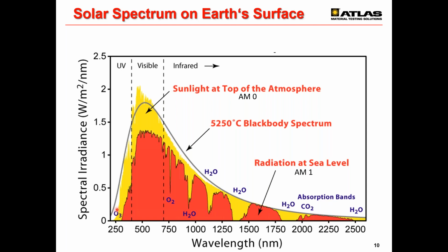What we in principle get when the sun is filtered by exactly one atmosphere is what we see in red here, the so-called air mass 1 sun. That's the case at sea level when the sun is perpendicular, so at the equator on the 21st of March, on a clear sky at noon. Then we have about this spectral irradiance distribution shown here in red, with the specific absorption bands of specific components of the atmosphere. I don't want to go too much into detail here.